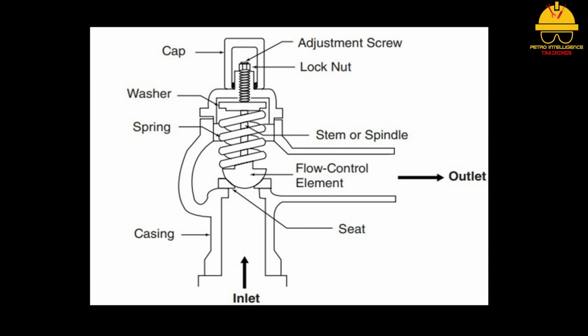Tremendous pressures can be generated in process units. Relief valves are designed for pressurized liquid service. They do not respond well in gas service. Relief valves are designed to open slowly. This is a poor feature for gas service. Another reason relief valves are not used in gas service is because of the damage high-velocity gas would do to the seats and disc.